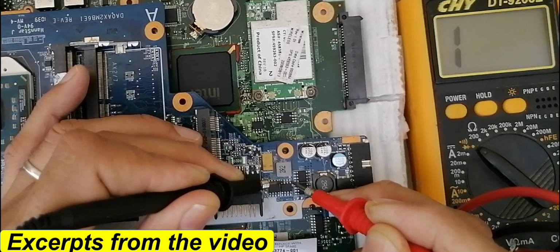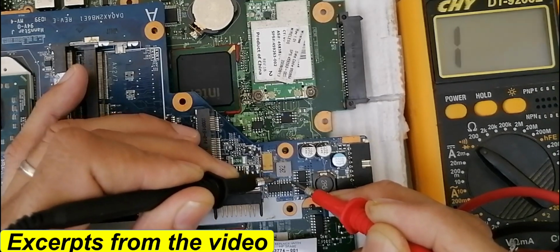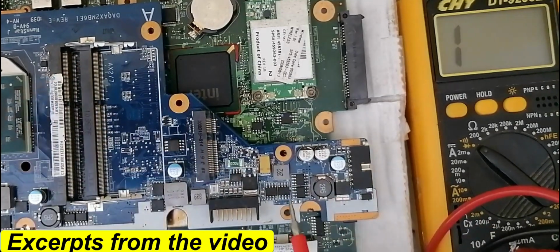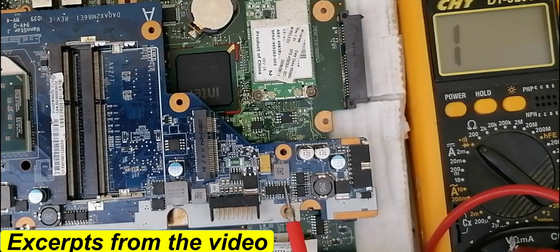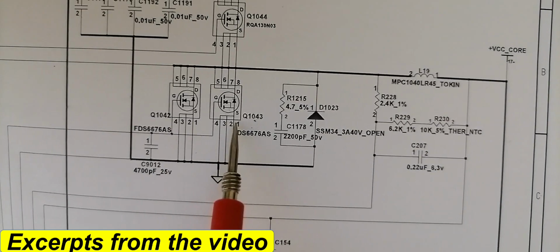So let's check the other pin. The 3rd one, we get continuity. The 4th one, nothing in the multimeter. We didn't get continuity because this is the gate. So these 3 pins are connected together. So this is source, exactly as we have here in the schematic.